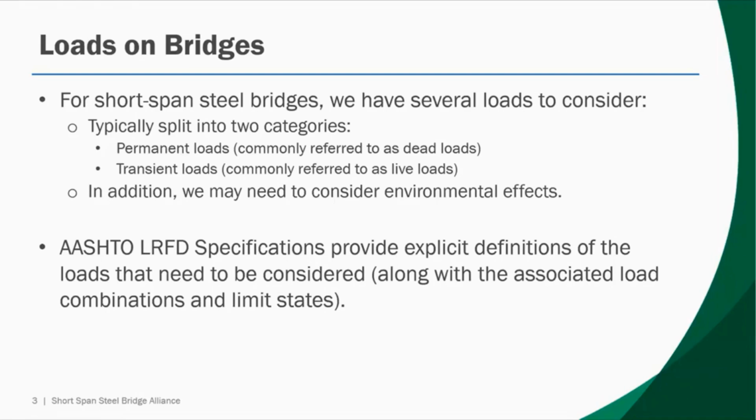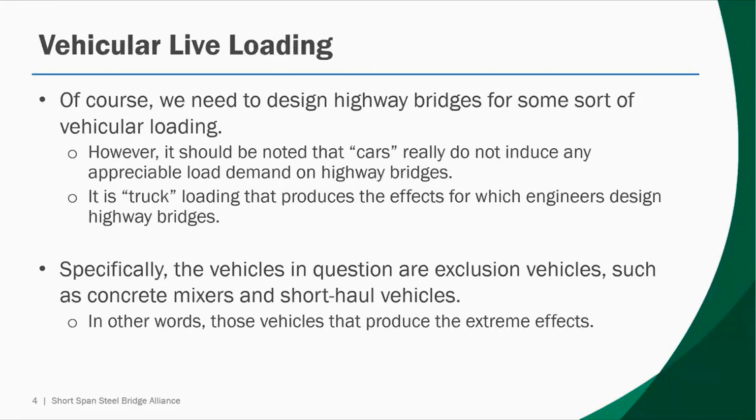AASHTO LRFD specifications do provide explicit definitions of the loads that need to be considered, along with the associated load combinations and limit states. If we focus on live loads, particularly vehicular live loading, well, of course, we need to design highway bridges for some sort of vehicular live loading.